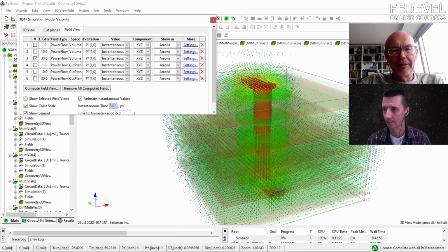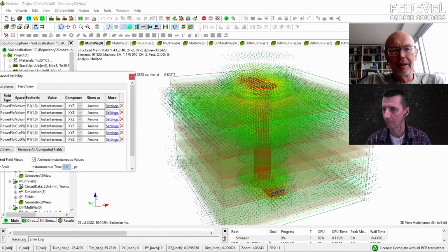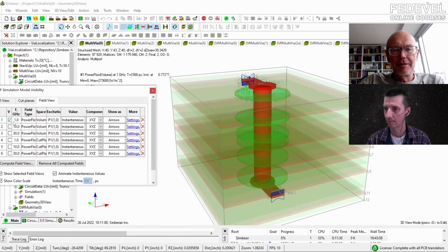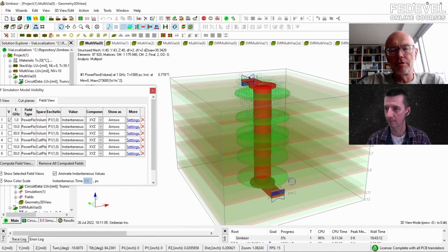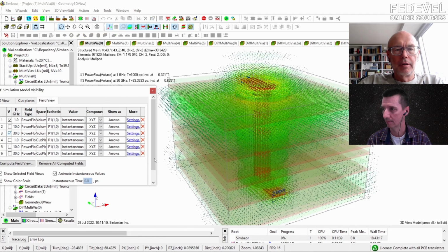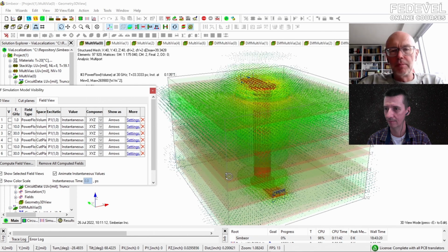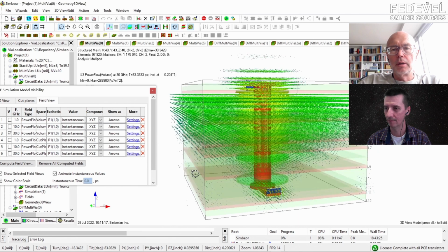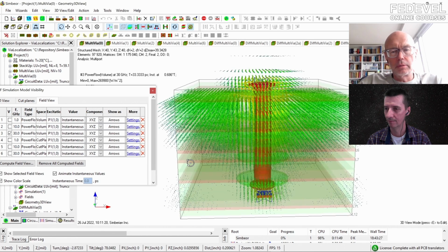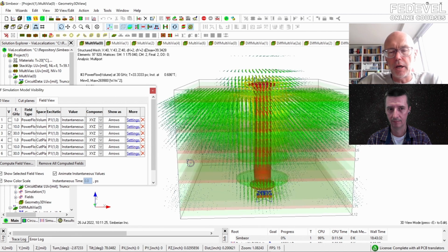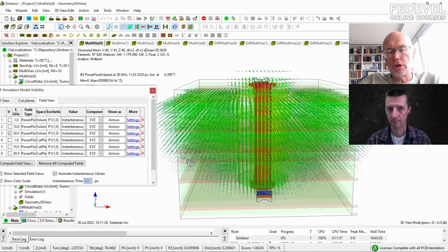You can see that now you can probably realize where I'm getting to. If you compare this, your energy gets through, and a very small amount is dissipated. But then when you get to 30 gigahertz, half or maybe more of the energy of the signal is disappearing. In reality, it may get back, but in the form of a different phase and so on. So it's always distortion of the signal.